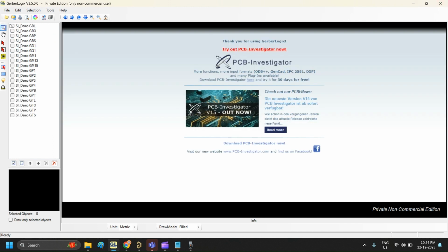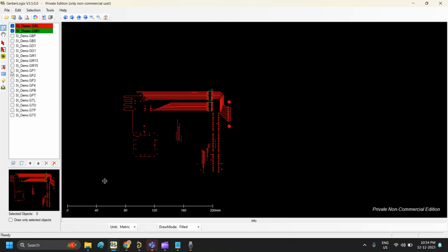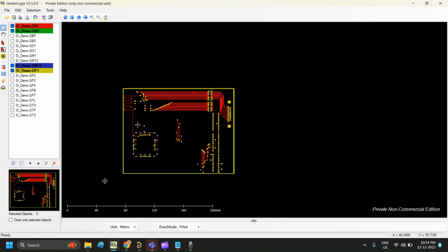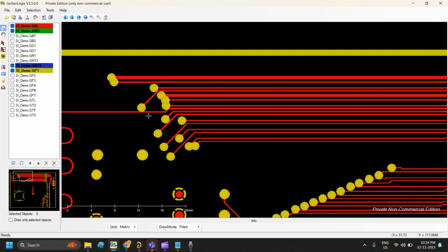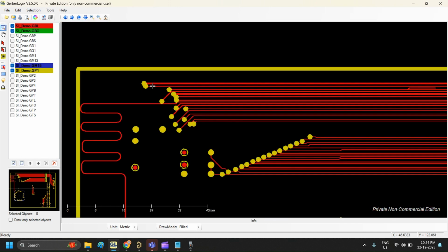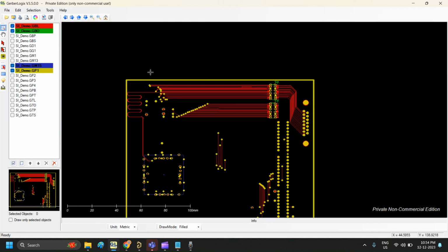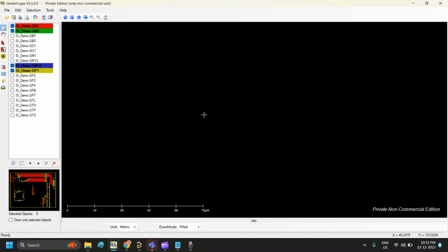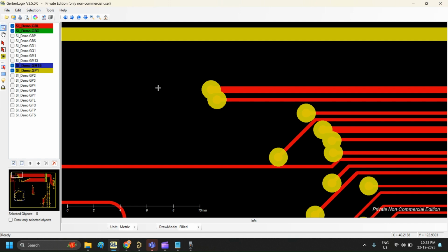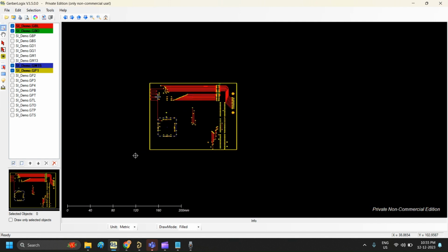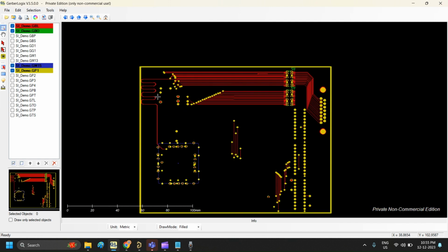I hope this video is helpful for you. And in Gerber file itself, why you are cross checking the Gerber file? Because you have to cross check whatever you defined in the PCB, whether it is reflecting correct or not, whether all the layers loaded properly, if there is any unit change error, something like that, you have to cross check.